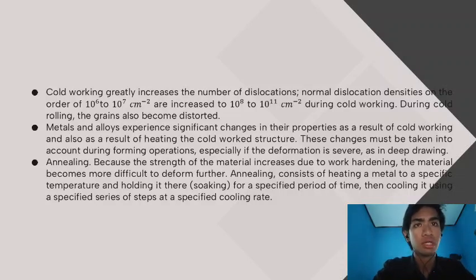During cold working, most of the energy is dissipated in the workpiece as heat. However, as much as 10% of the energy is retained as stored energy within the metal in the form of vacancies, dislocations, and stacking faults. The amount of stored energy increases with greater amounts of deformation and lower working temperature.